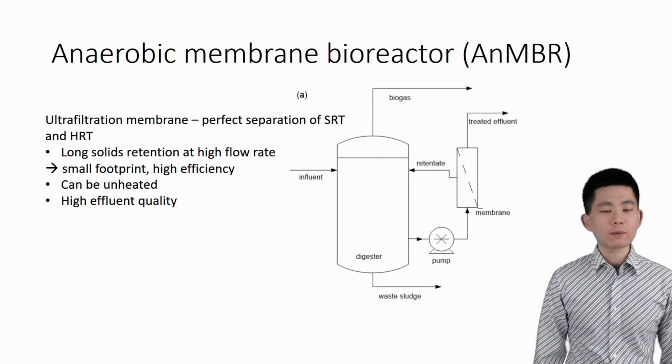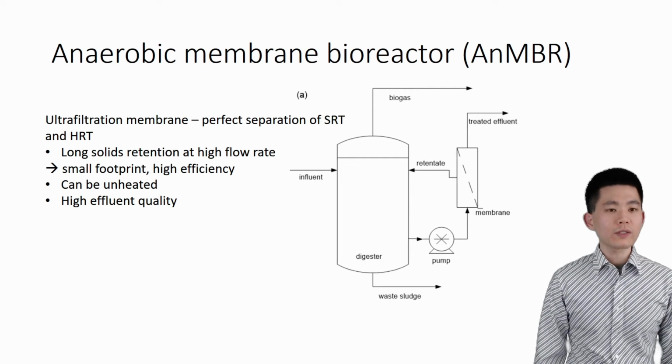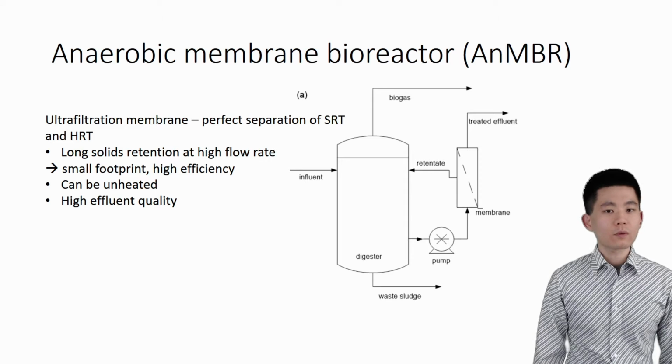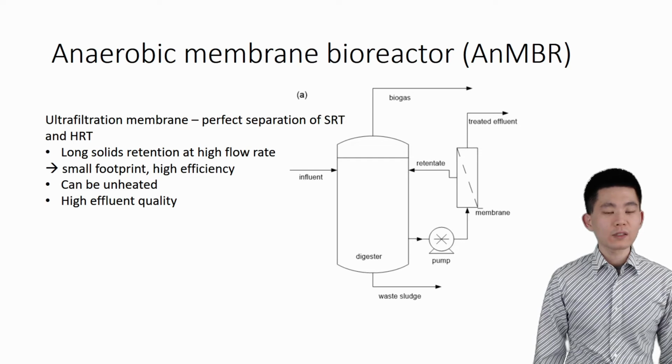This effective separation of SRT from HRT makes it possible to operate at a low HRT while maintaining a high SRT for thorough breakdown of particulates. Because of the long SRT, the reactor can be unheated to save energy.